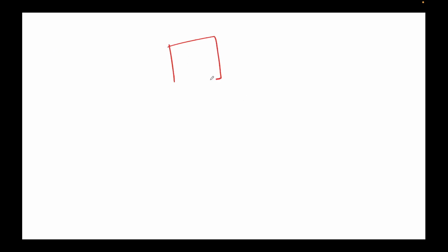So this JK flip-flop has 2 inputs, J and K, and then Q, and there's also a Q bar which I'm not drawing. Obviously there is a clock which is like this, and if you short J and K, then this is equivalent to nothing but a T flip-flop.